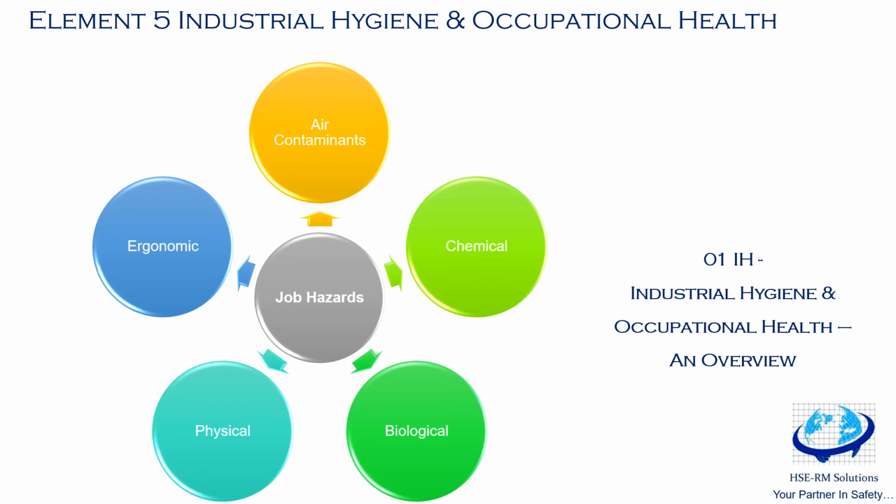Now what are fumes? These are solid particles generated by condensation, generally after volatilization from melted substances and often accompanied by oxidization. The particle size varies from 0.2 to 1 microns. Common examples are lead and zinc fumes.